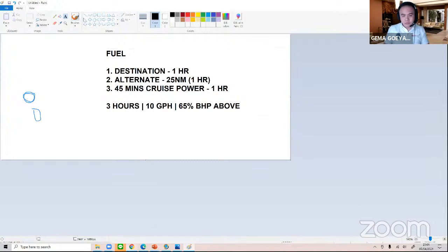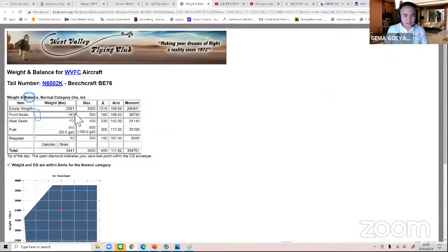And now I want to do the weight and balance. So everything is in order. It's based on your needs. My weight is 185, Cinta 125. I'm going to put the fuel as a full tank. I always do that if you don't bring much passengers and you're not intentionally bringing a lot of baggage. I always fly with the maximum fuel. It's 100 gallons usable fuel, so times 6 that will be 600.